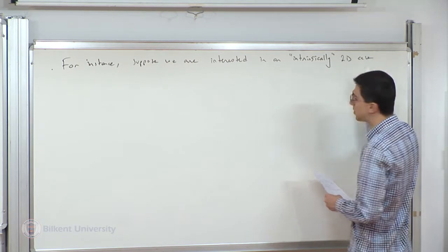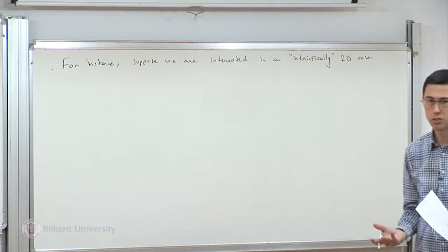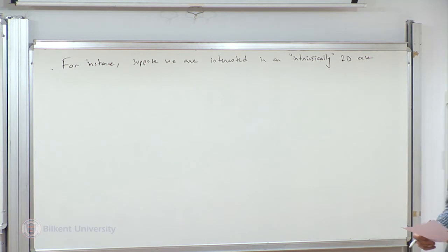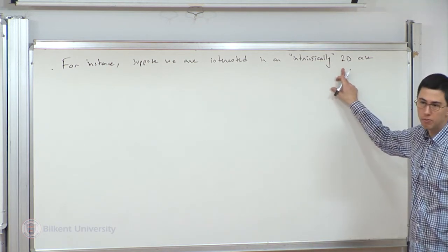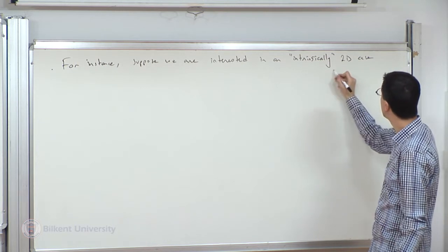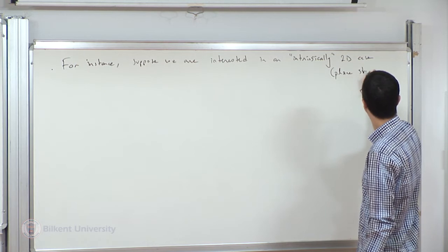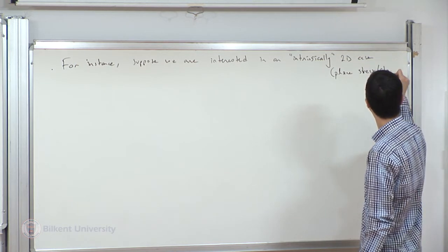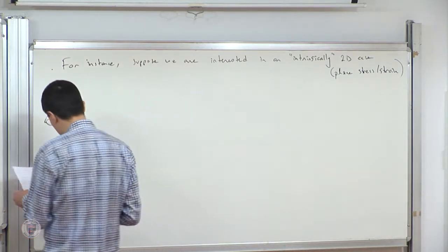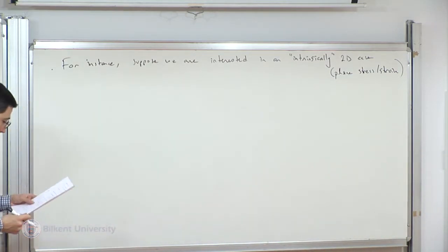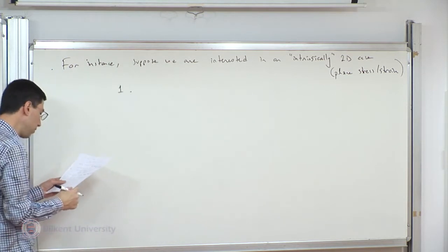Now, the world, of course, is 3D. So when I talk about an intrinsically 2D case, it means for analysis purposes, considering 2D is sufficient. So such cases are, you might remember from 231 and 232, plane stress or strain cases. When you have plane stress or strain, you don't have to worry about one of the indices, so you only worry about the remaining two.